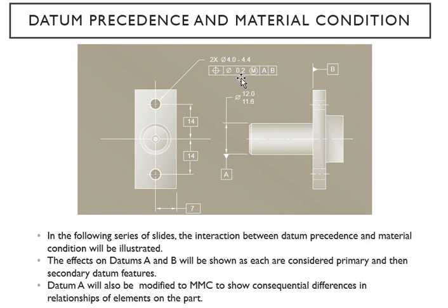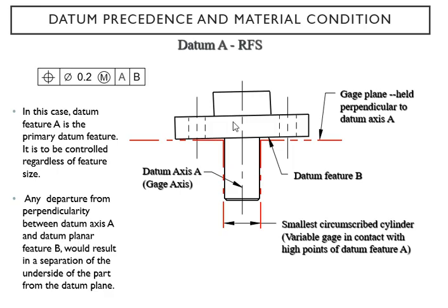And then here is your tolerance. Here is what that tolerance is referencing, right here in this reference control frame. You have two datums, which are A and B, yeah? So these are their surfaces. They are 90 degrees to each other, yeah? So this datum A is going to control that, and this is going to control this. All right, and then we'll get into an exaggerated diagram right here.